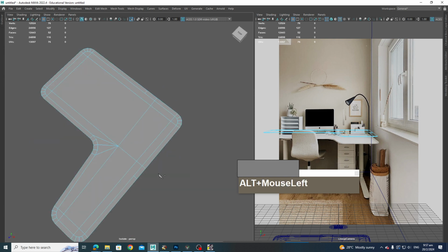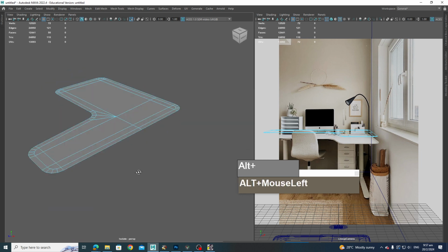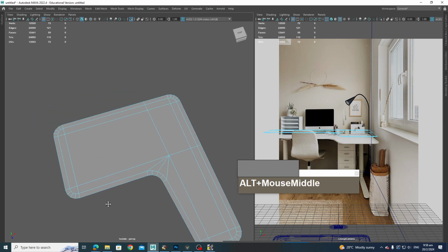Okay, now let's do some cleanup. Now we need to remove this edge. So go over to edge, select this edge, Control Delete to dissolve it. Please don't just press delete for edges, just press Control Delete. Otherwise you have floating vertices. And still got one more.